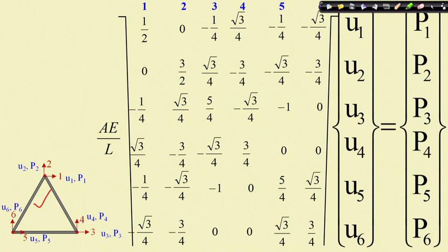Okay. So, whatever constraint we have, we have to substitute that information in the stiffness matrix. If you do not give this information, then this stiffness matrix is for the entire structure, assuming that every node has all the degrees of freedom. But if every node has all the degrees of freedom, the structure is not stable, and this is manifested by the fact that this stiffness matrix is singular, meaning we cannot have a unique solution.